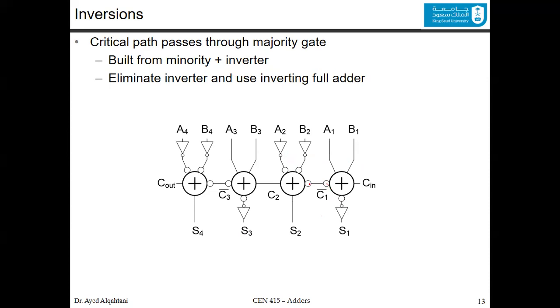Now the next stage is the other way around. The inputs actually have bubbles in the adder. Now focus on the circles only. So here they are normal, and here we have bubbles. Here we have bubbles in the input, and here we have normal outputs. Once you do this for 2 stages, you just copy and paste them for the rest of the number of bits.